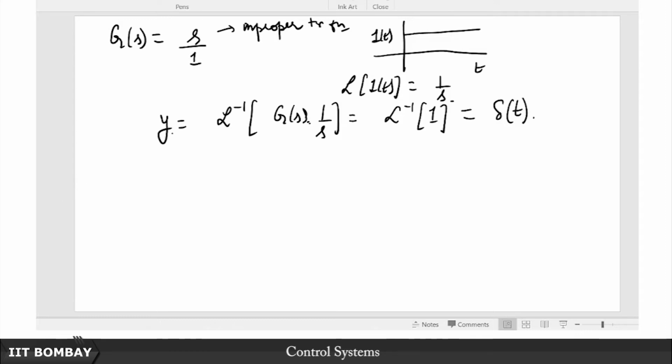So you see what happens the moment you start introducing these improper transfer functions, even for signals that themselves do not have such Dirac deltas, or in a broader sense, the derivatives of those Dirac deltas and the doublet function, and so on. Shouldn't really call them functions again. Never mind. You end up getting in your output these Dirac deltas. What's more is the fact that you're giving an input, and this sort of a transfer function basically necessitates the appearance of the derivative of that input in your output. What does that essentially mean?